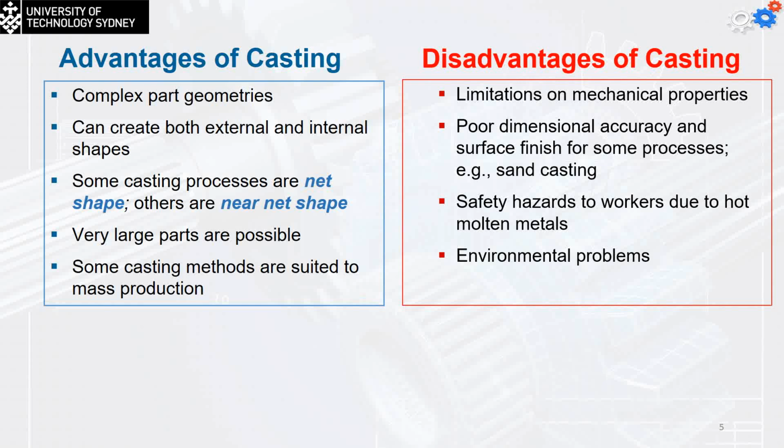We can overcome this problem when I do die casting, because you saw that we pressurize the chamber. With the cavity, the metal will simply be pressurized. But you remember that we said we can only do it with soft materials. We cannot do die casting for steel.